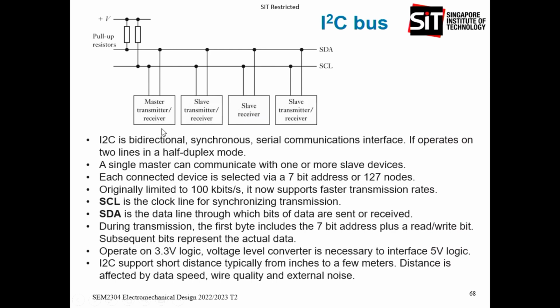The first information that you put onto the data bus will be the address of the party that you want to send the information to. You put out the address, and then whichever slave has this address will have to start clocking in the information.